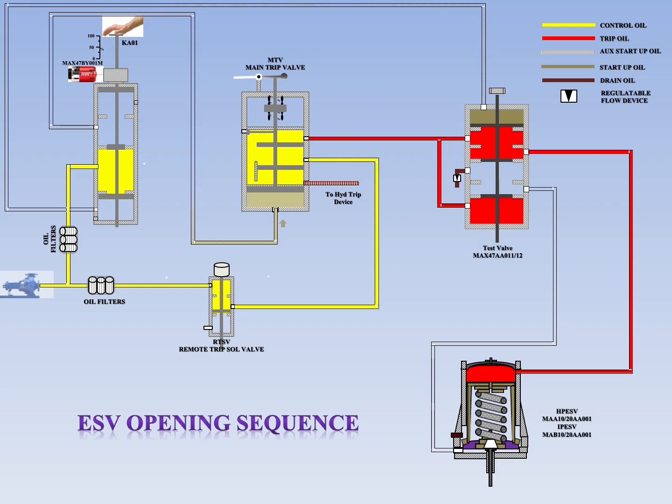The pistons of the test valves are forced upwards by the restoring springs, whereby the trip oil flows to the space below piston disc Ka02 and slowly drains from the space above piston Ka01. The pressure difference thus occurring lifts both piston and piston disc together into their upper end positions, thus causing the main and reheat stop valves to open.